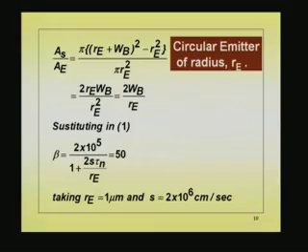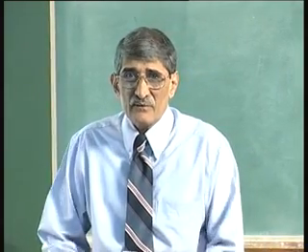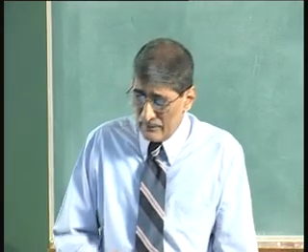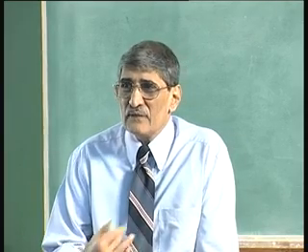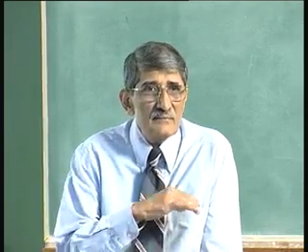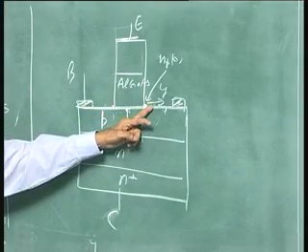If at all you have to get good passivation, you have to remove that oxide completely and deposit some oxide on the top. Now, if you deposit oxide, people try to deposit nitride, oxide, etc. on the surface. No question of putting oxide, because that oxide will react with gallium arsenide to release arsenic. So, there is no chance for you to use silicon dioxide even by deposition for passivation. See, what I am trying to point out is, over here you must deposit some layer.